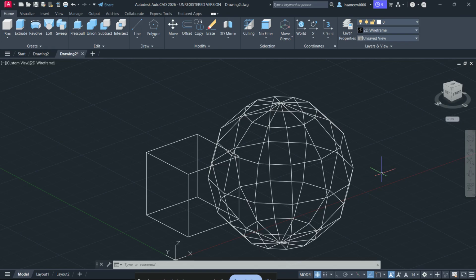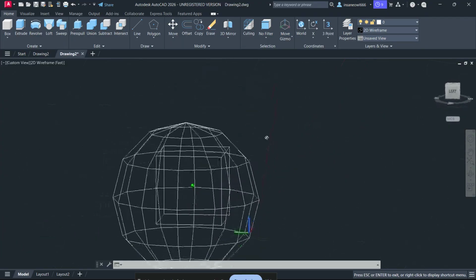You should also try the chain option when using FILLETEDGE. Instead of selecting every edge individually, the chain option helps AutoCAD calculate a continuous smooth path across connected edges. This often improves the result because the software treats the edges as one flowing operation instead of a bunch of separate calculations. If the corner is complex, this can reduce the chance of a modeling failure.